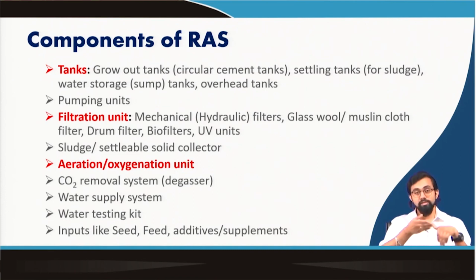Sometimes tilapia can sustain a very low dissolved oxygen level, but there are certain types of fishes which cannot sustain a DO level of less than 4. So in order to go for the aerator unit design, you have to understand what aquatic species you are culturing in your system.